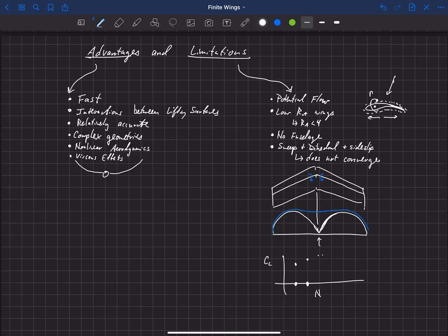Well, as I increase the grid resolution, I would expect this to level off at some value, and so we can estimate what that is. There's actually a method called Richardson extrapolation, where if we have 3 solutions along this curve, we can extrapolate where this solution is going out at n equals infinity. If I had an infinite number of nodes, and it offers that kind of behavior, then we would call that a convergent solution, and the rate at which that converges is the order of convergence. Okay, so anyway, that's what happens for a straight wing.